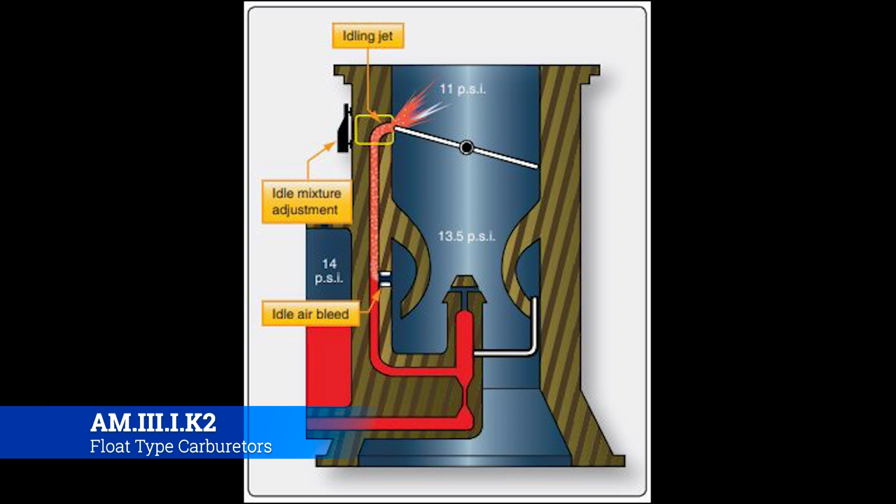And for flight operators, especially for flight training, you're going to end up pulling the power to idle a lot to simulate different things, and you don't want to get into an unsafe situation where you're doing, let's say, an emergency approach, and you're like, okay, we've done all the things that we want to do, let's go around. You put the power back to it, and all of a sudden, man, you don't have it anymore, right? So the idle is really, really important, and all it really is, is a bypass.